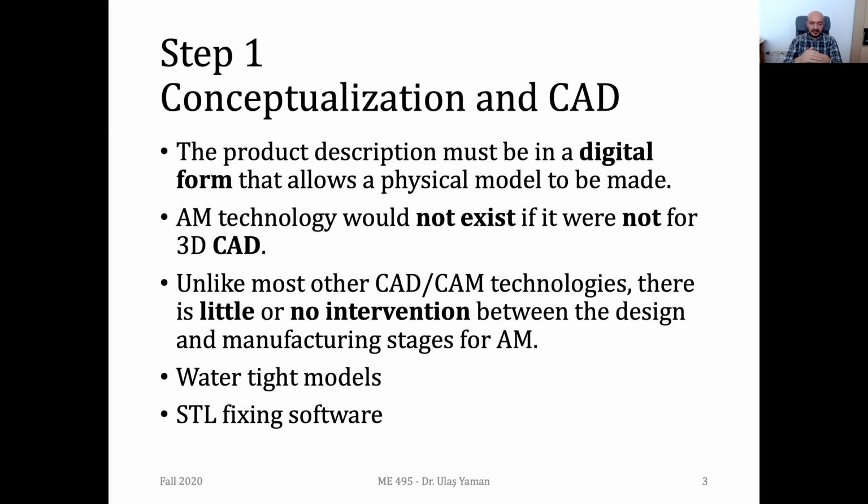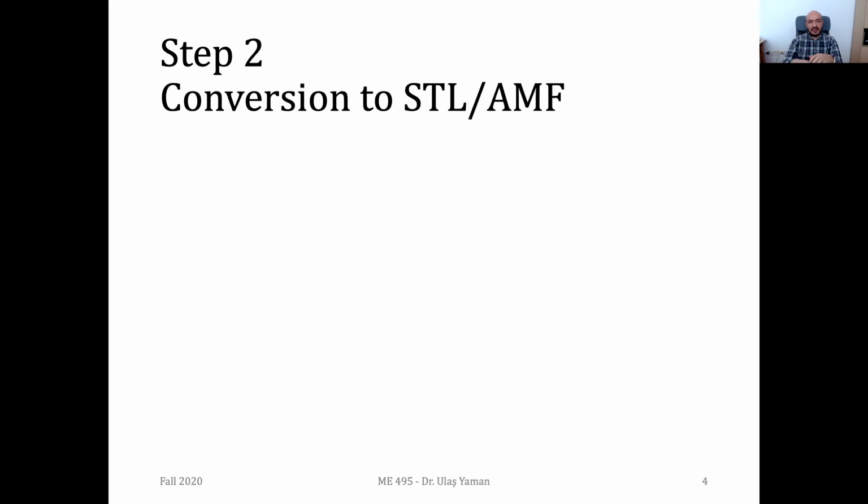This is also possible. Once you do scanning, then you can directly start from the second step, not from the first one, since most of the scanners output STL files or mesh files. You can directly start from this second step.